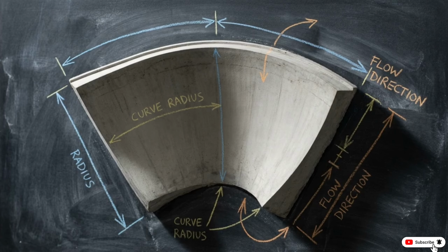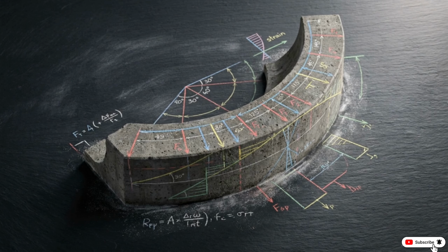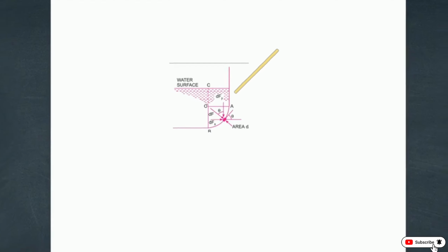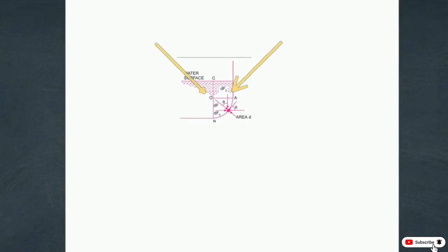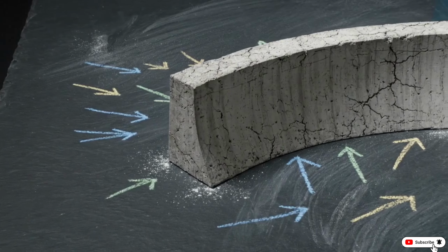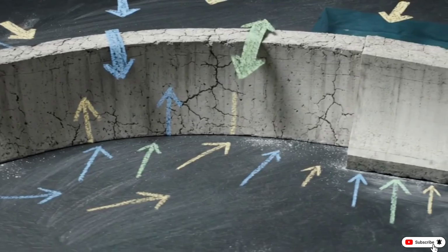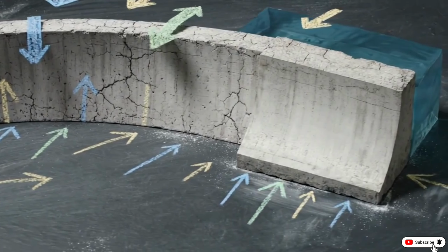Modern dams and sluice gates use structural curves to handle massive loads, which prevents the use of simple flat surface pressure equations. To solve for these shapes, engineers break the total force into components, a horizontal push and the downward vertical weight of the fluid resting on the curve. Combining these two vectors reveals the resultant force, the total physical load impacting the structure at a specific angle. Calculating these multi-directional vectors allows engineers to design curved dam faces that handle the specific, localized weight of static water.